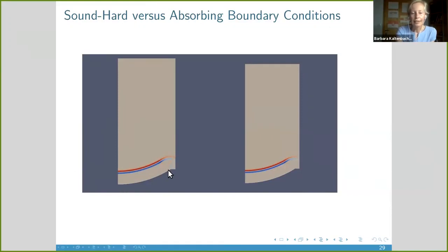this is again just a cross cut, just half of the cross cut here. The wave is excited down here, and then it will travel through the domain. But in our computations, we have cut the domain here. So this is just a symmetry axis, so there's no problem about this. But these boundary parts are the essential ones. If one just puts homogeneous Neumann or Dirichlet conditions, then the wave will be reflected by them.